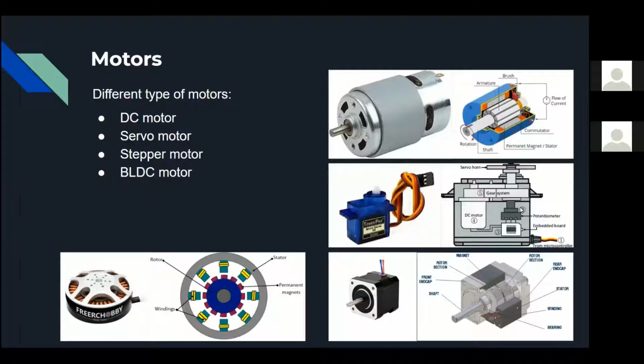This potentiometer is just a variable resistor whose resistance varies with the change in the knob, correct? So when the knob changes, the resistance also changes. The microcontroller will keep monitoring the resistance of the potentiometer, and it will correlate the resistance value with the angle of rotation. So it's like a complete loop, a closed system.